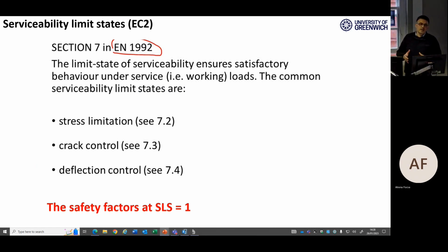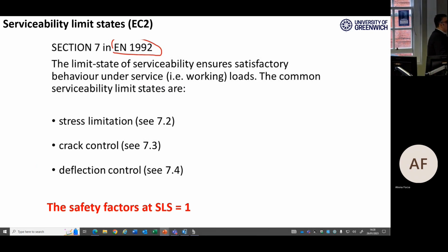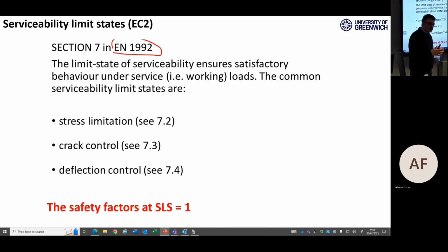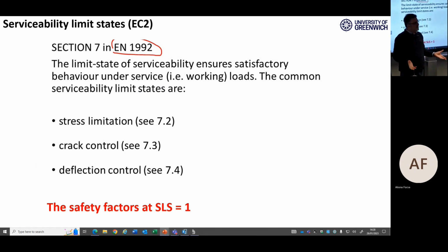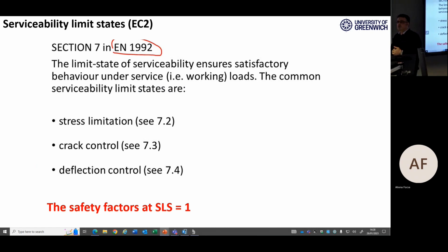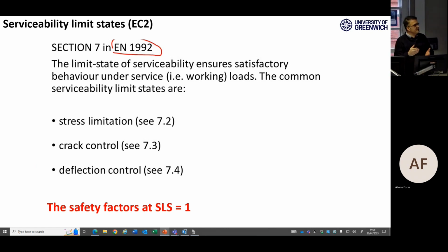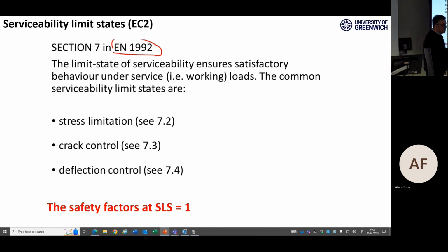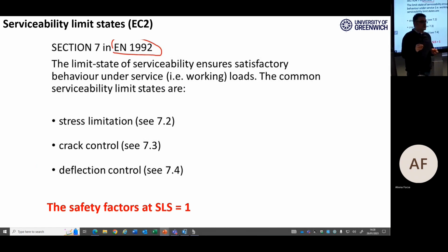However, on the other hand, the serviceability limit state means the day-to-day life of the structure, not that kind of rare situation. It means that today we are under this roof and the structure should work reasonably for our purposes, right? So we don't need to use those amplification factors, 1.35, 1.5, to increase the loads. All those coefficients are 1. You just add every kind of load that you have, dead plus live plus.